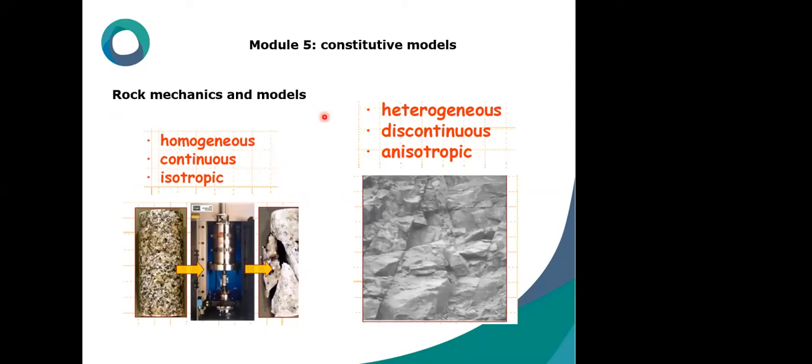Okay, rock mechanics. Simple approaches that take into consideration the discrete specification of rock shall be described. Due to geotechnical conditions and the nature of rocks, there are issues in the design of tunnels in rock medium that are not in the design of tunnels in soil medium. Soil can be considered homogeneous, isotropic, and continuous, but what about rocks? There are generally cracks, joints, and faults that make the behavior of rocks complicated.